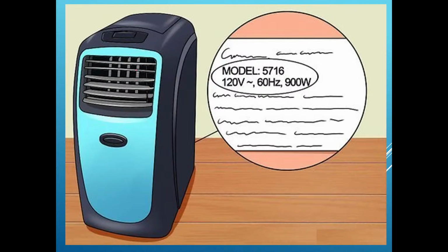I have one more image. Here, this is an air cooler, and you can see the back side. This sticker is on the back side. Its voltage, frequency, and power ratings are provided here. So, the rating of an electrical appliance indicates what? It indicates the voltage at which the appliance is designed to work and the current consumption at that voltage.